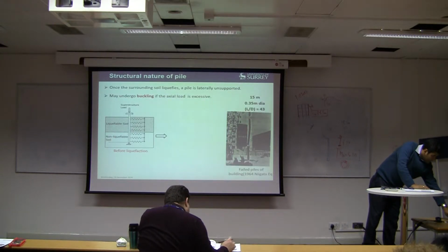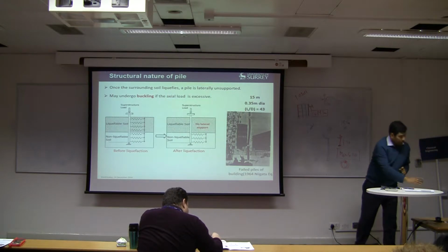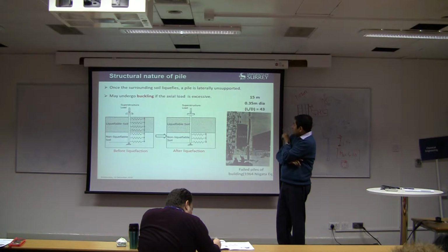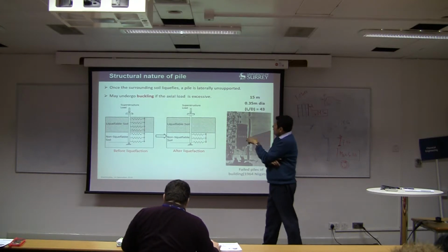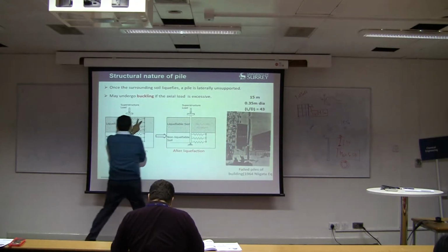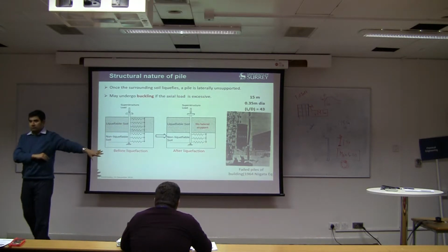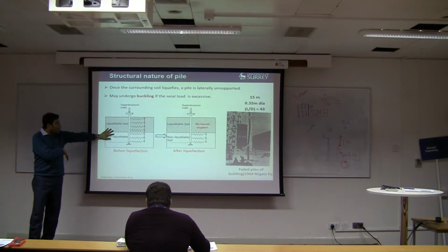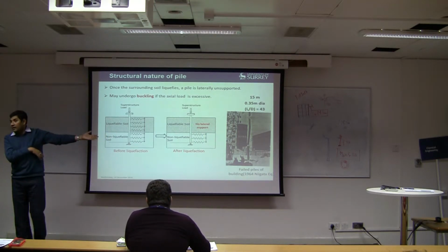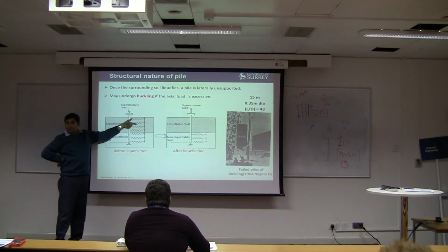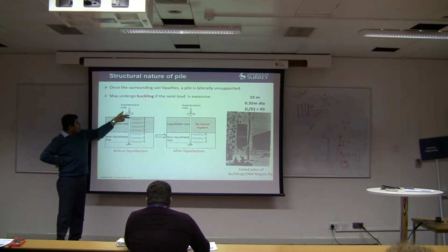And so if one soil layer liquefies, here is the spring approach that we all use for design. That's currently the approach everywhere. If you look into routine design, they will use this spring approach. The reason being, through the spring approach you can model the soil layering.